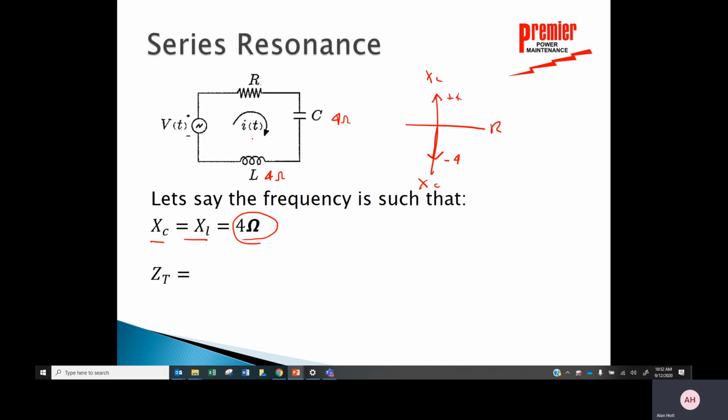So basically, at this resonant frequency of this simple series circuit, these two cancel each other out. So X sub C plus X sub L equals 0. It's a short circuit. And that's important for us to understand. At this resonant frequency, I can take a jumper wire from here to here and jumper it out. And so the current would flow in that circuit through the resistor like this back to the source. Effectively, there's no capacitance or inductance there.